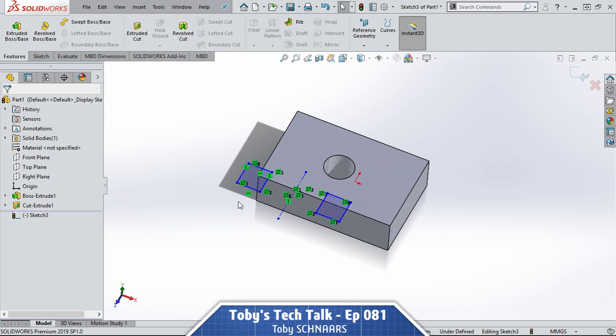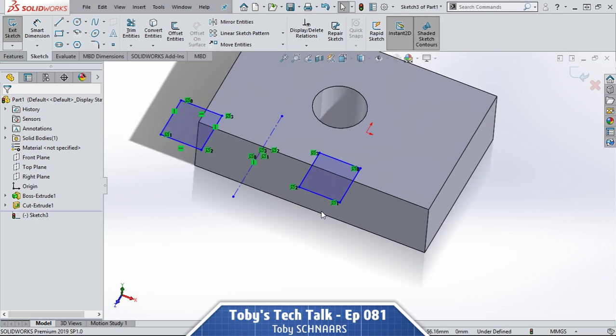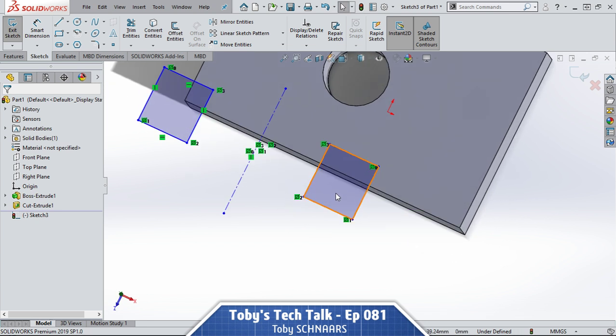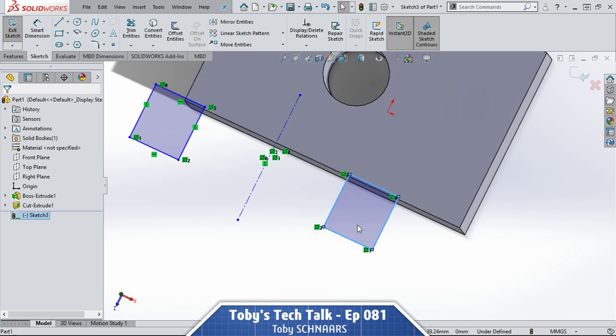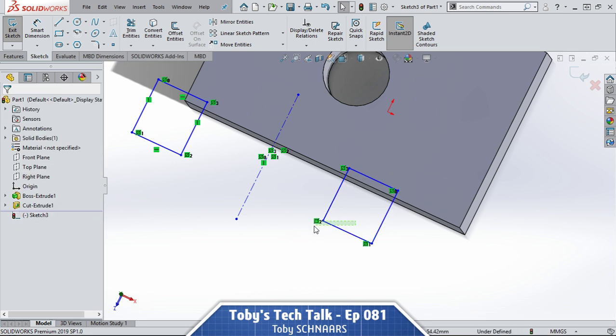Next, I want to briefly talk about the use of Instant 2D and shaded sketch contours. It's important to know what these functions do. Shaded sketch contours shades in the sketch here, and it changes what happens when you're inside the sketch and drag. I personally do a lot of crossing selecting to pick corners like so, and you lose that ability if you have the shaded sketch contours. Although you gain some other functionality, it's for that reason that I typically turn it off.